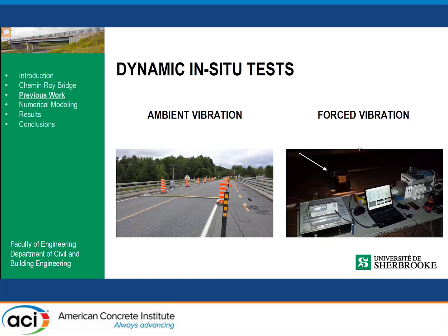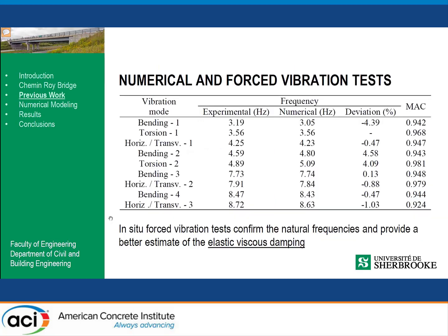You get better definition of the response curves, and hence better frequencies, mode shapes, and damping results. But you do have to close the bridge. That's why you see it's pretty dark. We have to do this at night. So for the three bridges that we tested, we did the ambient vibration test during the day, and then we closed the bridge and at night we did the force vibration test.